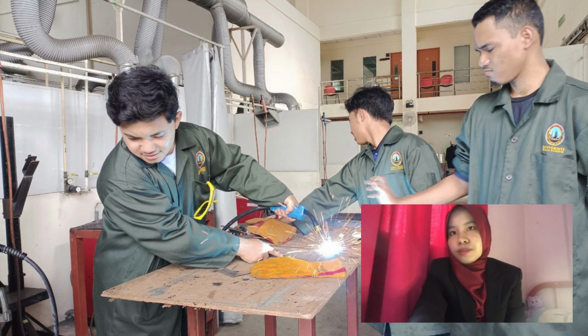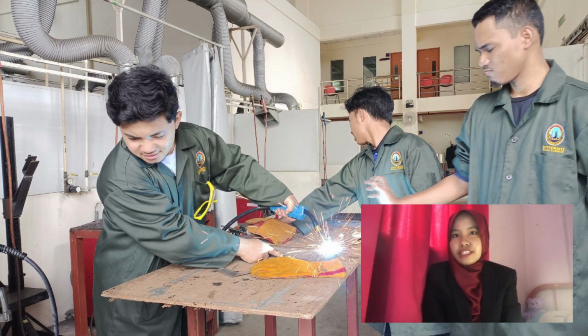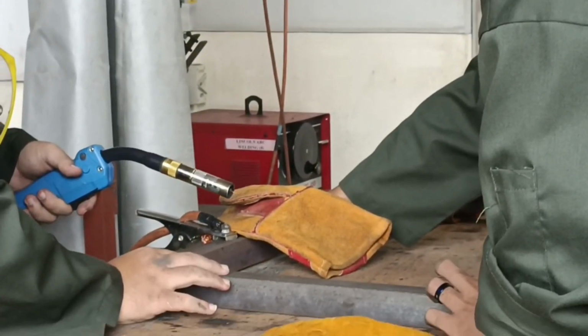And make sure the material to be welded is flanked by welding clamps to run the arc, and weld the pieces together without worrying about movement in the sheets. The clamps enable us to weld pieces together in a tight alignment.